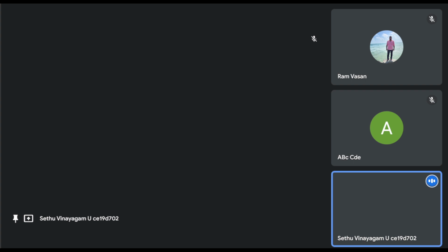Warrant 8 is depending on the road network. And the final warrant is for intersections that are near a grade crossing. At grade crossings, which means at the same level there is a crossing happening and near that there is another intersection. So that is warrant 9.